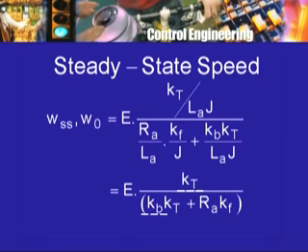Roughly you can see it as follows: there is KT here, there is KB KT here. So if I cancel KT, I get KB in the denominator. So this looks like voltage divided by back EMF constant, but that is dimensionally speed, so it tallies. Same thing of course should hold about the other term, RA into KF divided by KT. I leave it to you to verify that dimensionally this equation is correct.